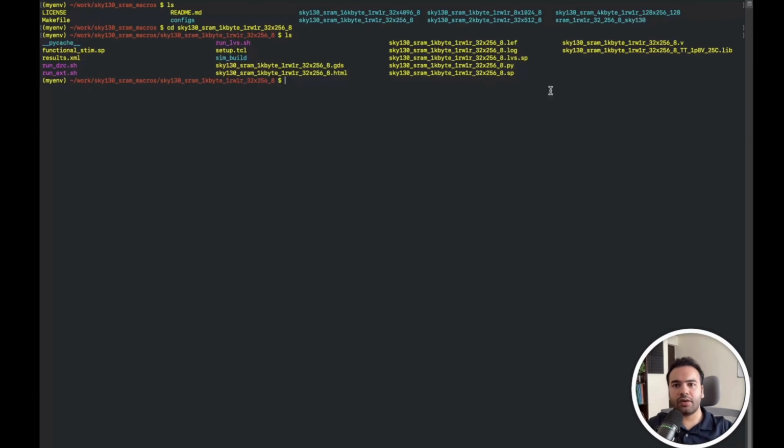What we're going to do now is open the Verilog model of the particular cell, and take a closer look at how this cell is implemented. We would then create a top level module which would instantiate this cell, and then a cocotb testbench to read and write into the cell and look into the waveforms.